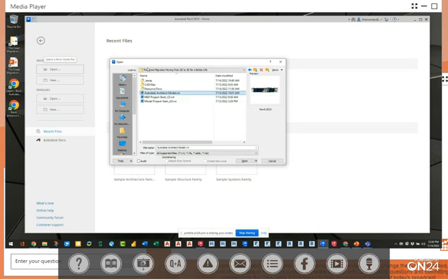The other reason why opening is so important is because of this audit checkbox down here at the bottom, audit, okay? Now in 2020, if you already have a little bit of Revit, this audit checkbox gives you this ominous warning that says this operation could take forever and it should be used for periodic maintenance of large files and preparation for upgrade to a new release, right? And that is valid, but if that's it, like you're opening up a Revit 2015 file and you're trying to upgrade it all the way to 2023.